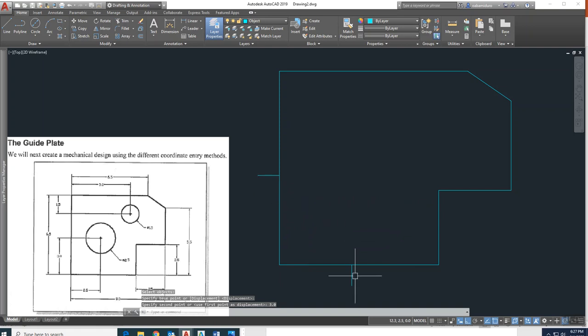Okay, I want these two lines to meet. We know we can use that fillet command again. Under radius, left click, and we have 0.0. You can type in 0.0, then hit enter. Then you can left click by selecting this, left click by selecting this, and those two lines intersect and join.